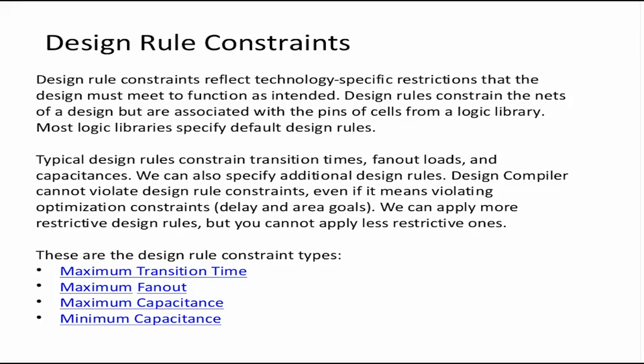Design Compiler will try to calculate the delay, but it will result in extrapolation, and consequently some error will creep in. This is why we say that the design rules have to be met to ensure the functionality of the design. If the design rules are not met, the timing calculation that the tool does is not reliable.